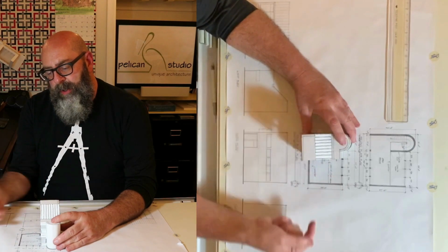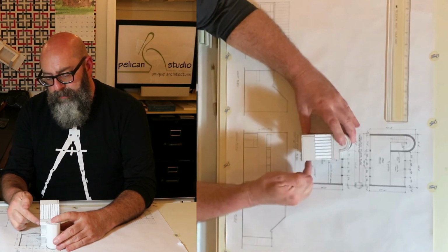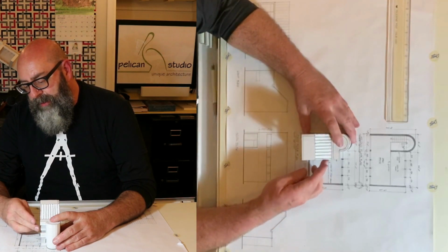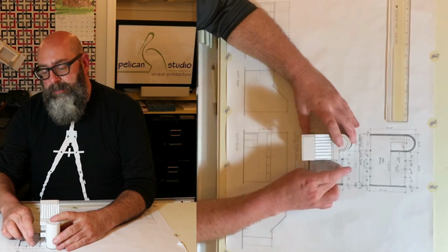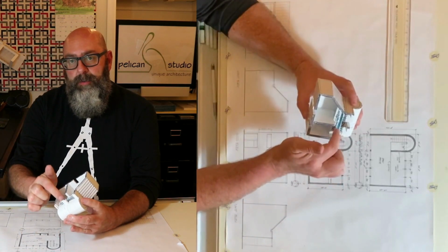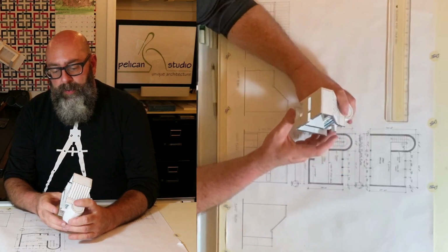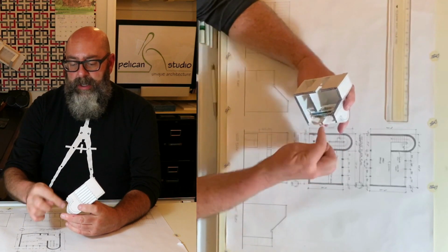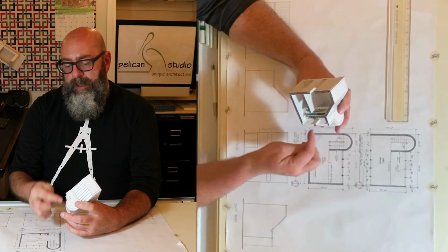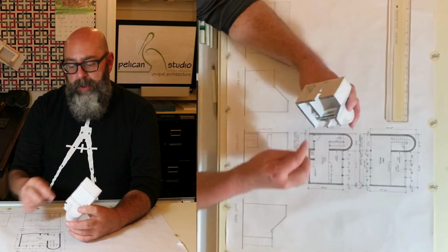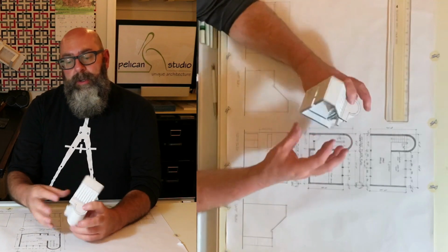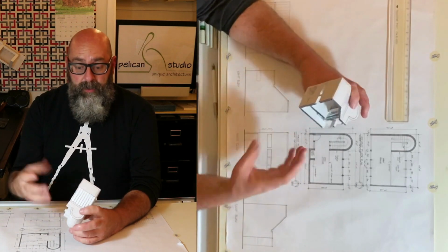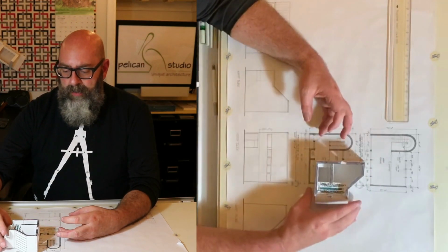So when I cut the building this way and I look this way, now I see the floor slab. No, I don't see the countertop, but we all know what countertops are like. I see the edge of slab, I see the window wall, and I also see my feature wall. Now, what I could do is also show in hidden dashed lines how the steps go up, there's a landing, and then the steps continue up. And I could show that in a dashed line. So this section gives me the best opportunity to show the most, to help describe what's going on. So this is the section I'm going to draw.